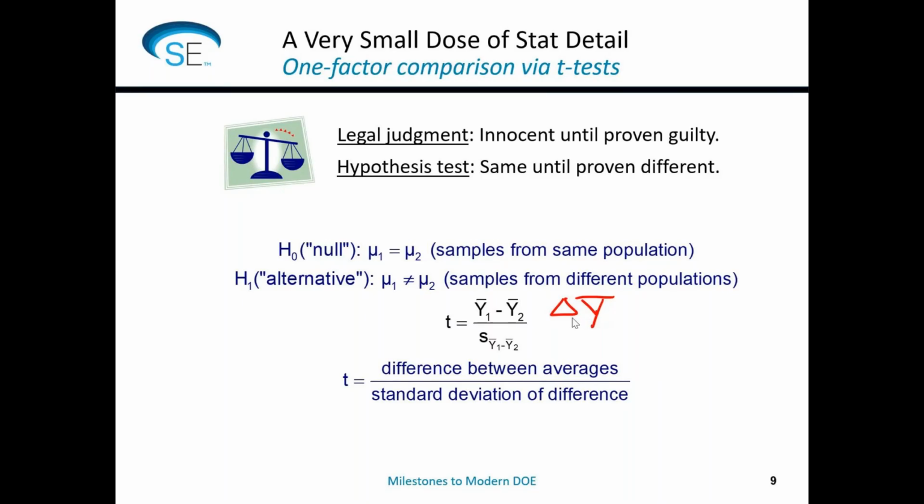I would do at least four of each to make sure that the distribution of the averages will become normal by what's called the central limit theorem. If you do a sample size of four of each at a minimum, but maybe more depending on the power that you need, I do some work on this in quality engineering to figure out how many samples I really need, collect those samples, and then we get into this statistical test called the null hypothesis, H sub naught. And this is a way to try to eliminate bias.